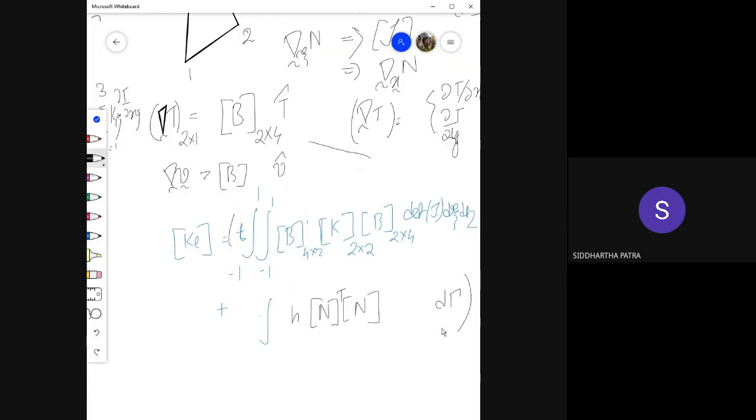So this is what the expression of the stiffness matrix should be. Next comes your force vector. The force vector, other than the reaction force vector, or now what would be reaction in case of thermal analysis? At each node, wherever we know the temperature, there is an unknown heat flow rate. That is the scalar Q. Unknown scalar Q. Basically the reaction heat flow rate QR acting at each node wherever we know the temperature. If the temperature is known, then this QR is not known at that node.